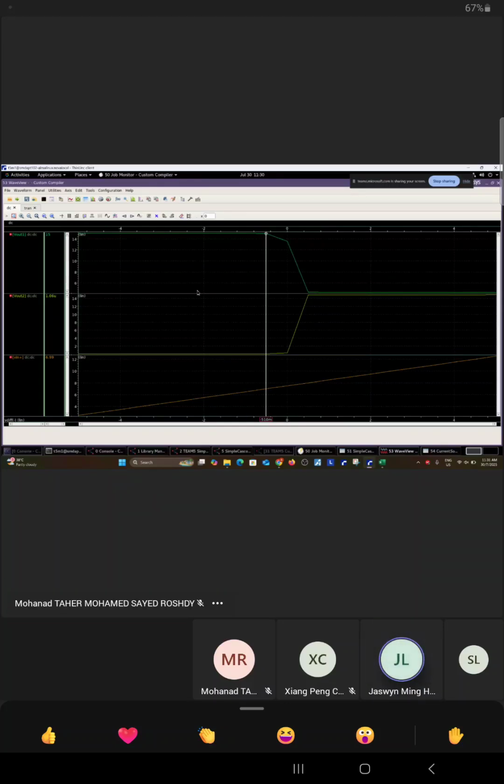So already the gain is so high actually. What's the gain so high? To be fair, I think the gain is very high. From what I can see, perhaps 0.4 is good, because I think maybe the audio signal only has an amplitude of a few millivolts. Yeah, if the VDIFF is only a few millivolts, then this is a good range already.